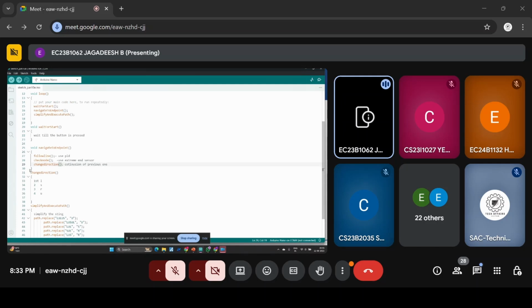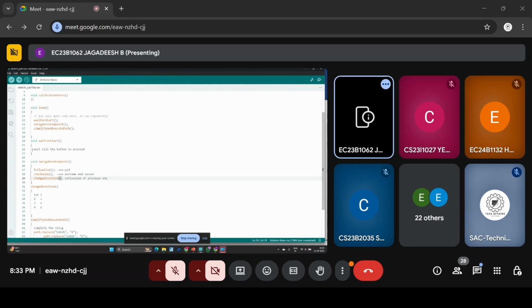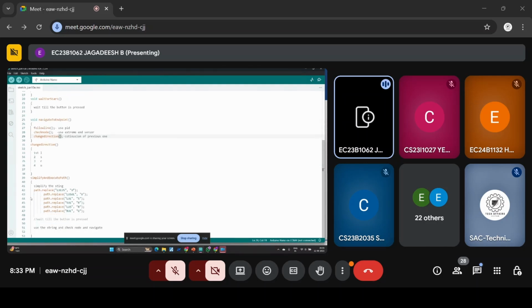While the bot is going along the line, it will know the directions. There will be an array where it stores left, straight and so on, in whichever direction it is going. Then there is a small algorithm which reduces the path. This algorithm handles U-turns and such. After simplifying it, the bot will run faster on a more optimum path.